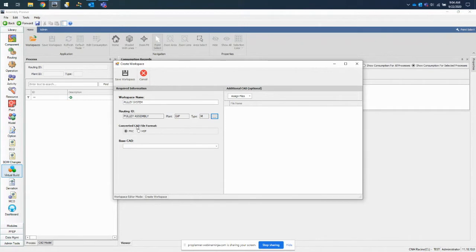When we do that conversion, we have a choice of using one of two different file formats. One is called PRC and one's called HSF. Let's put it this way for today's purposes: the difference being PRC will offer you probably a little higher quality, better resolution, and things like that. With that may come a small performance hit. However, HSF is quite nice. It does convert well, but you sacrifice a little quality for the sake of speed in that case.